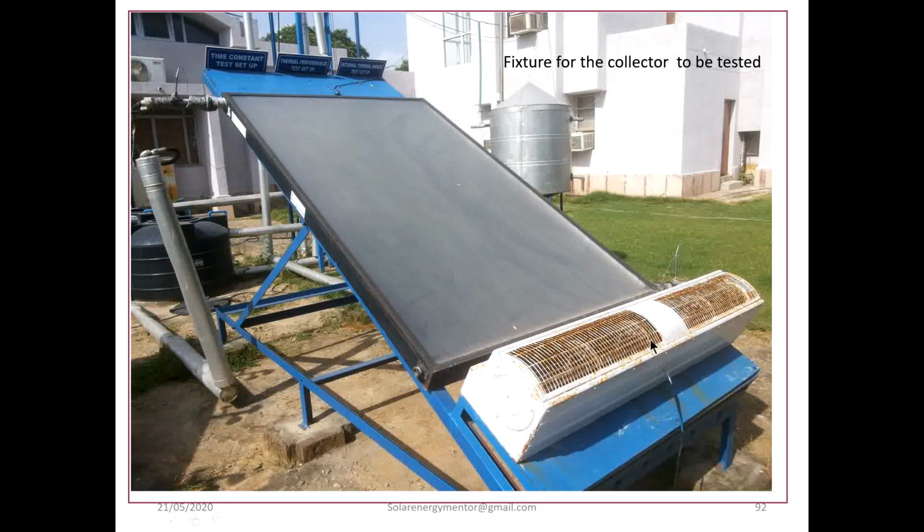Now you can see the fixtures at the National Institute of Solar Energy, Gwalpahari, which is also a testing center for collectors. These fixtures are built for testing the collector as per Indian standards. In this fixture, the collector to be tested is mounted, and then you can conduct the time constant test, thermal performance test, and internal thermal shock test.